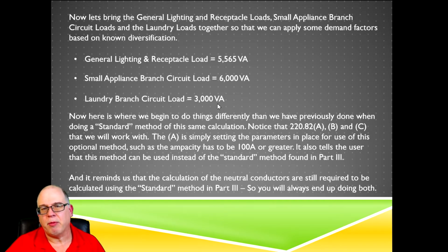The other thing to remember is that if we use the optional method and our calculation comes up to be less than 100 amps, guess what? We can't use the optional. We have to use the standard, because the optional is limited to 100 amps or greater. Just remember that. I don't want to get you messed up in dealing with that.